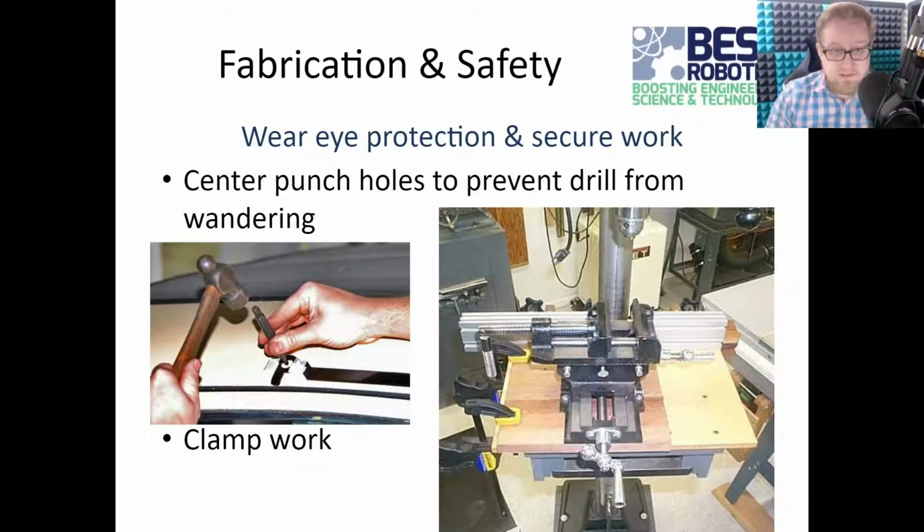As always, safety is extremely important. We don't want any of you getting hurt while you're working with these tools. And while you're being safe, it will also make the end result of your final piece better as well. If you're taking your time and you're thinking about what you're doing, what you create is going to be better than if you rushed it. And one good way that will aid in safety and also effectiveness is center punching holes you intend to drill.